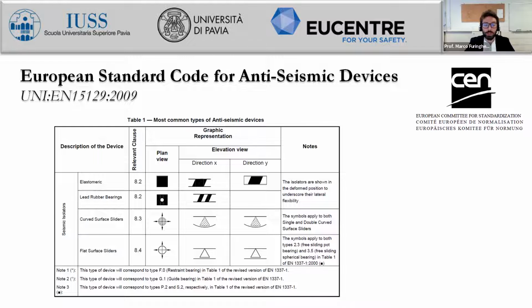together with elastomeric bearings, because we will see that in real applications, it is quite uncommon to find a number of elastomeric bearings equal to the number of structural bearings for a given building, rather than bridge structural systems.